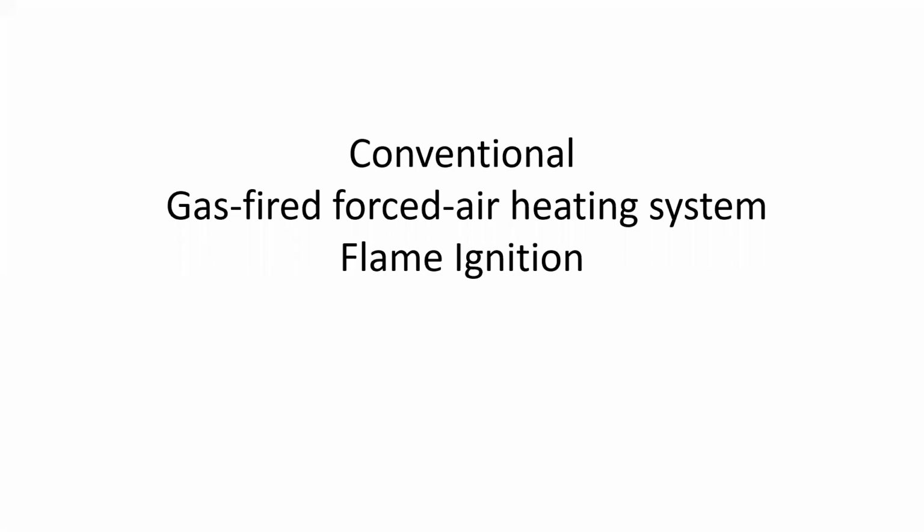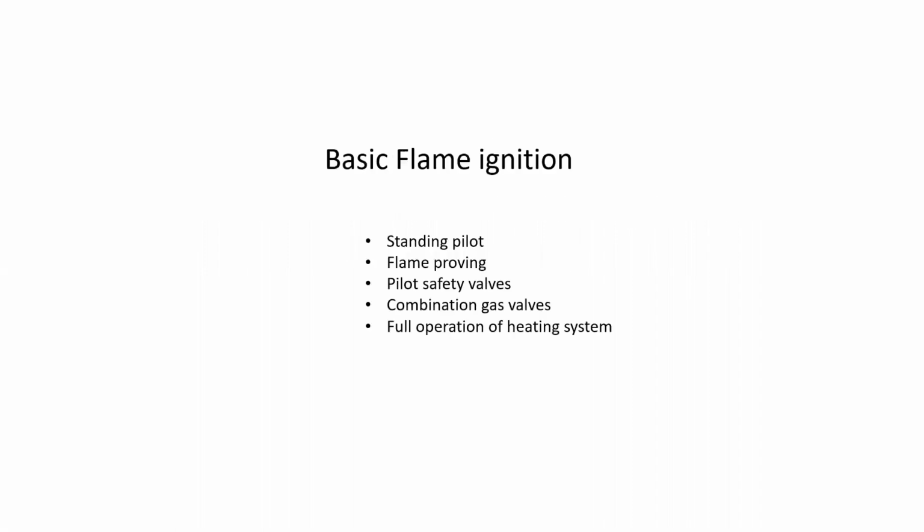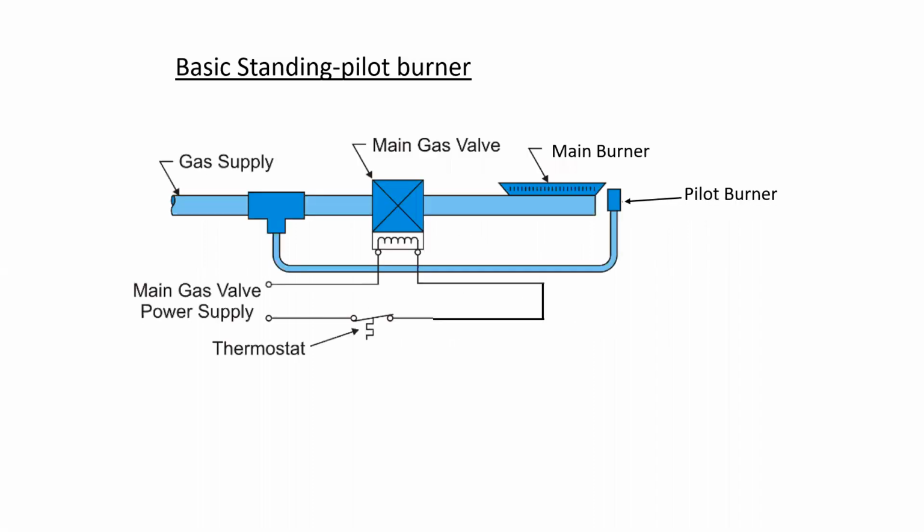Conventional gas-fired forced air heating system flame ignition. In this presentation, we're going to be looking at flame ignition in the form of a standing pilot, what that means. We're going to look at flame proving. We're going to look at pilot safety valves, combination gas valves, and finally, we're going to finish with the full operation of a heating system.